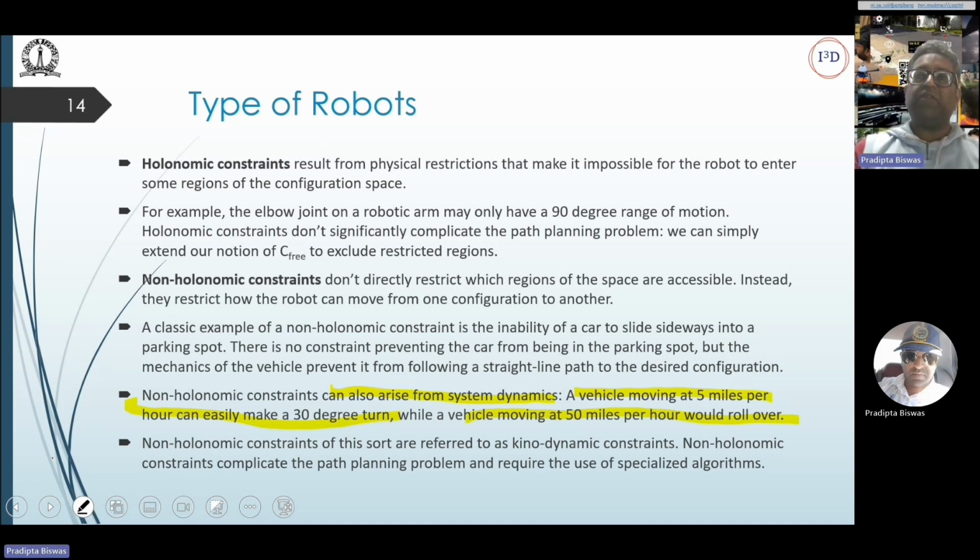So for holonomic constraints, we can encode them, and they are not going to change based on the task or situation. They remain the same. So I can define the obstacle space considering, say, the linkage structure. But it's more difficult to do it for non-holonomic constraints because there we also have to take into account the task. So I just wanted to make you aware of these definitions.